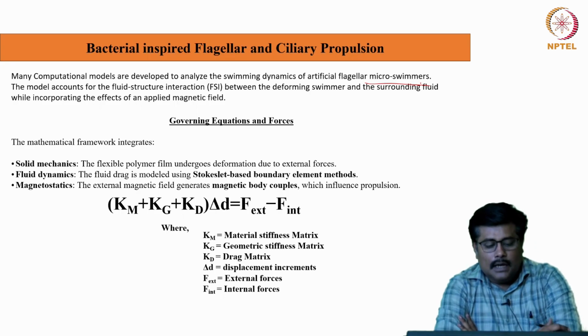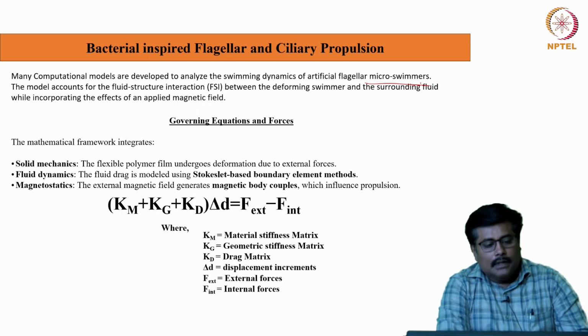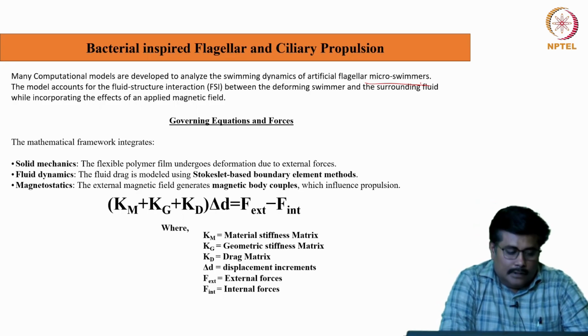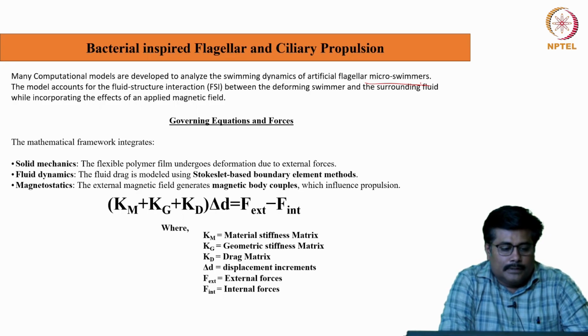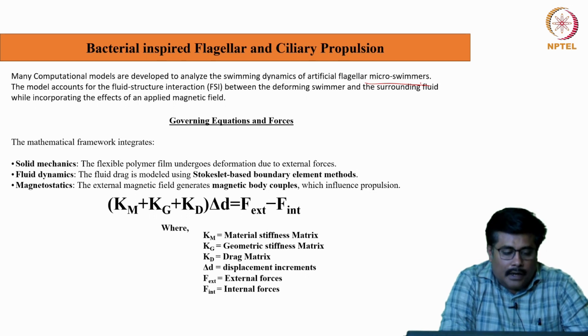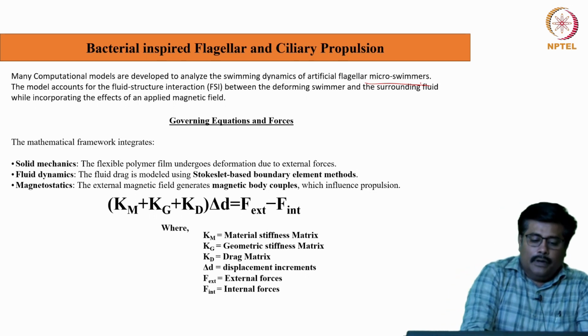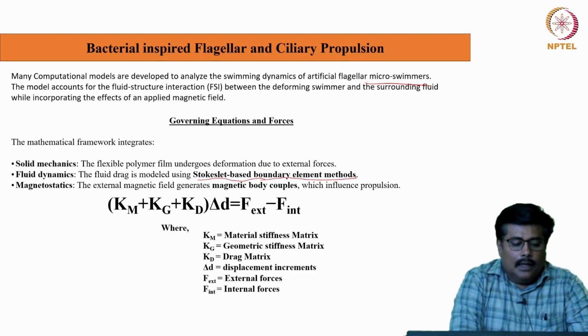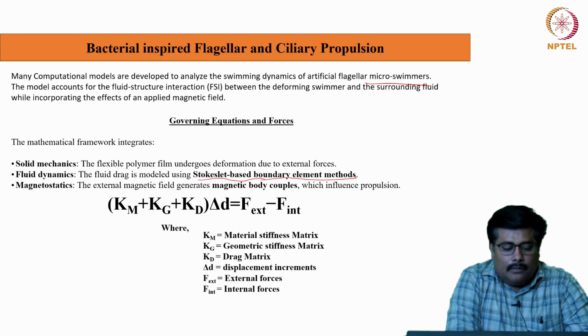If we closely observe the equation behind this, the mathematical framework integrates solid mechanics, fluid mechanics, and magnetostatics. From the solid mechanics point of view, the flexible polymer film undergoes deformation due to external forces. With reference to fluid dynamics, the fluid drag is modeled using a Stokes-let based boundary element method. With reference to magnetostatics, the external magnetic field generates magnetic body couples, which influence propulsion.